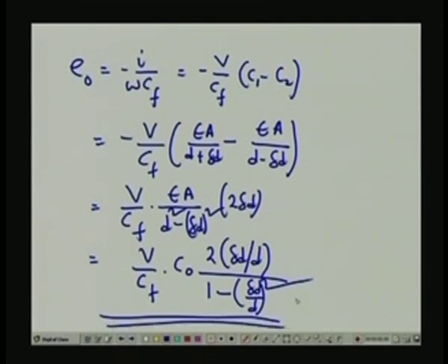So, we have seen in these cases how we can use a differential pressure pickup, how I can use a sensor which has a differential output, and how I can connect it in the bridge; all those things we have discussed. Basically in instrumentation you will find these capacitance sensors have 3 uses. One is as displacement sensors, as we have seen, either permittivity variations, variations of the area, or variation of the separation between the plates, number 1.